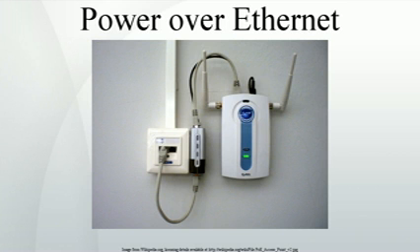In addition to standardizing existing practice for spare pair and common mode data pair power transmission, the IEEE PoE standards provide for signaling between the power source equipment, PSE, and powered device, PD. This signaling allows the presence of a conformant device to be detected by the power source, and allows the device and source to negotiate the amount of power required or available.